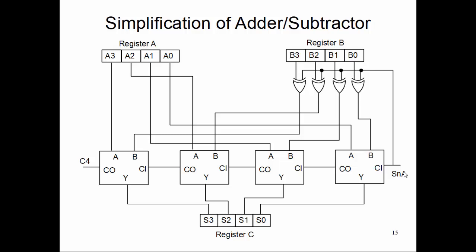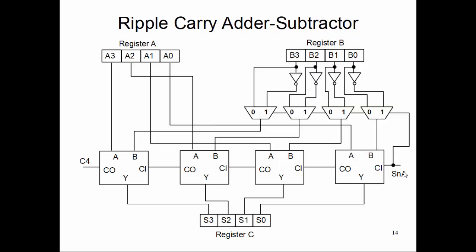We started with a complex one just from the spec and our first initial intuition that, hey, we have this hardware selection capability to multiplex, so let's use it. But we also readily realize this has many basic level logic gates, many extra transistors, compared to if we just look at the logic relations between different components of any digital circuit.